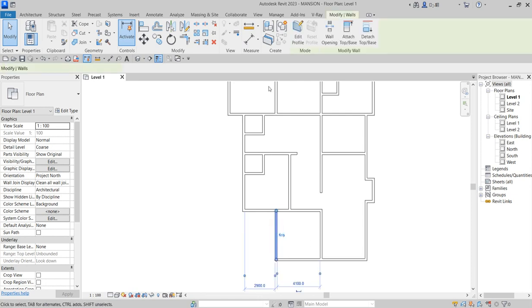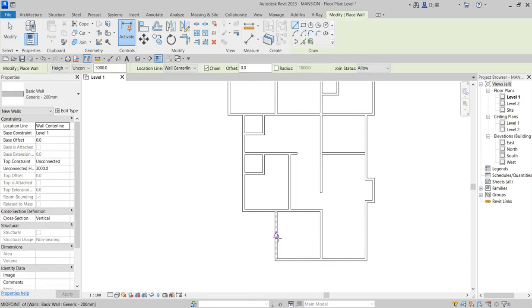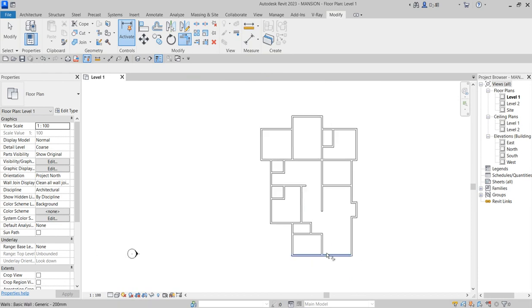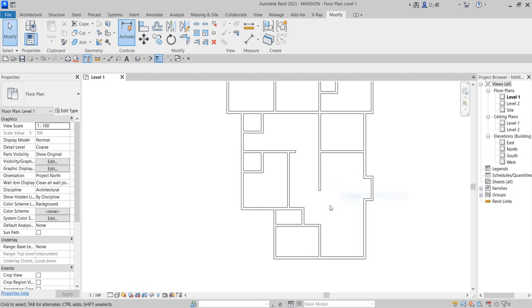So the visitor toilet, I'm going to create it by saying okay, it stays here. So I'm giving it a moment, without moment like that. Okay, that's visitor toilet and this one is anti-room. So I'm creating that into space. Good. So I am trimming what is trimmable. So this space is now left open.